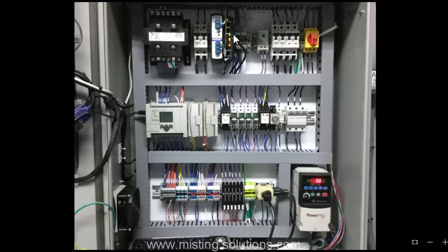So if the internal temperature within this control cabinet gets up to 80 or above 80 degrees, it starts this fan right here. So this is a cooling fan. It is 120 volts AC, and it is another item that comes off this circuit breaker right here, this 120 volts AC circuit breaker. The other item we haven't talked about is this time delay relay right here.